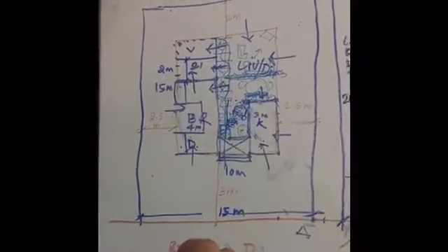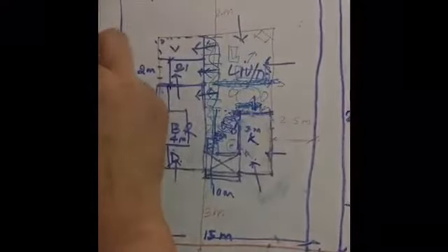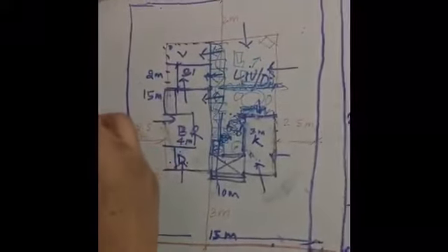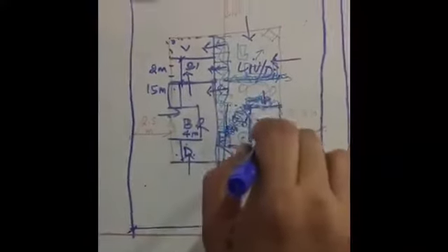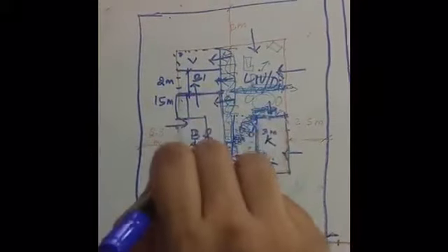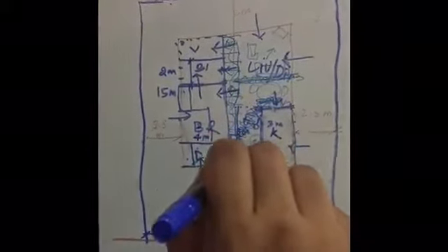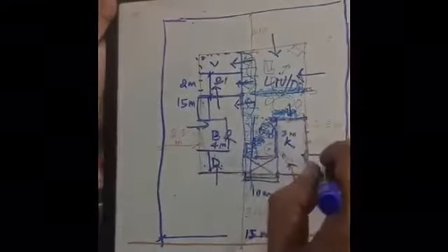Let me know if you have any questions. When we sketch in the exam, what I suggest is first design the space as a sketch, decide the dimensions of the rooms, and then start actually drafting on the drawing sheet. Sometimes when you start drafting on the drawing sheet, you realize that this is too big, too small, or too tight.